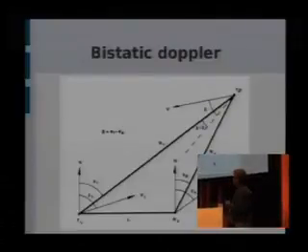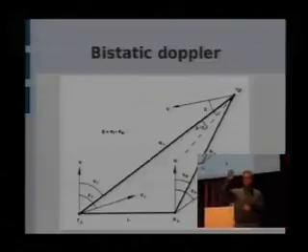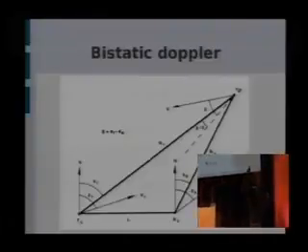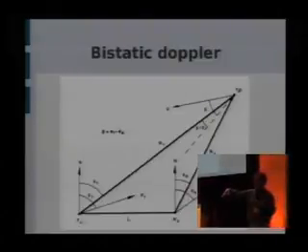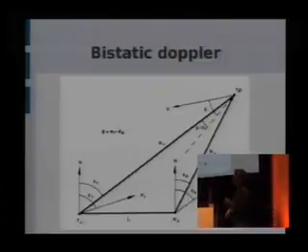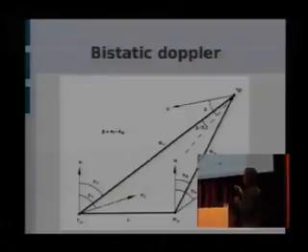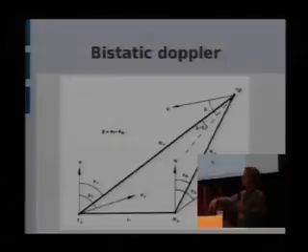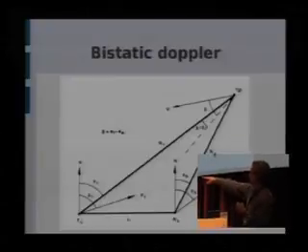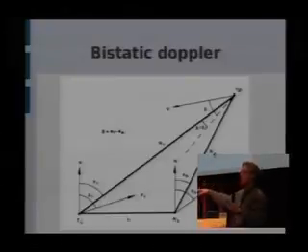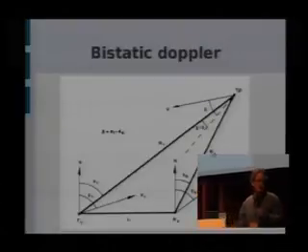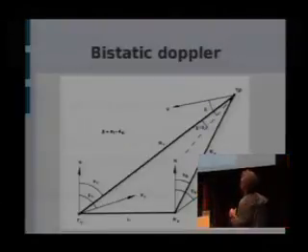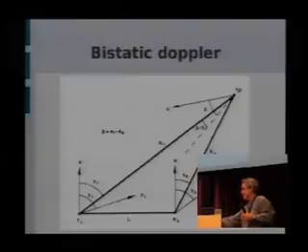As a sort of footnote, people here have been on boats with radar systems, and they have this sea clutter where the waves start showing up and you can turn the knob down. Well, you can start messing with the clutter, meaning what stuff is reflected to you off of the ground, by varying the velocity vectors for the transmitter and receiver, since you control those. So there's some cool stuff that comes out in the fancy case.